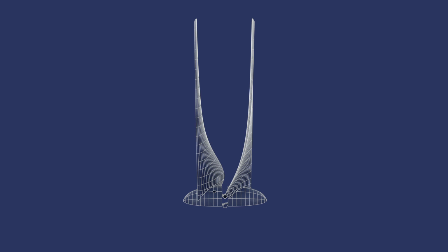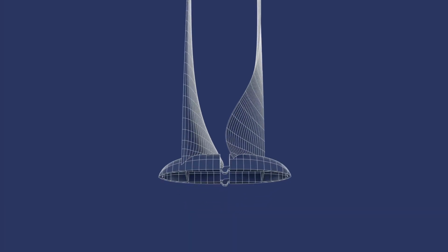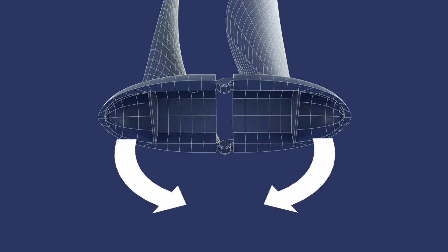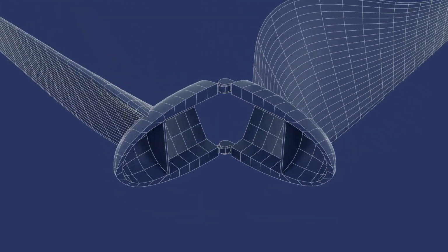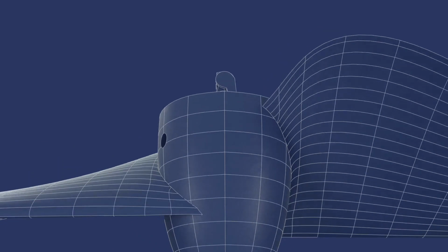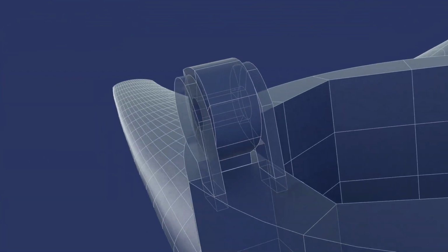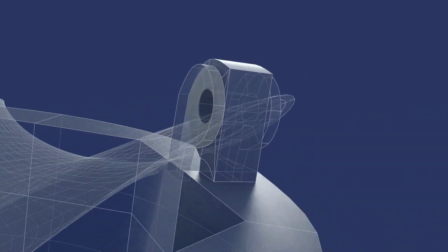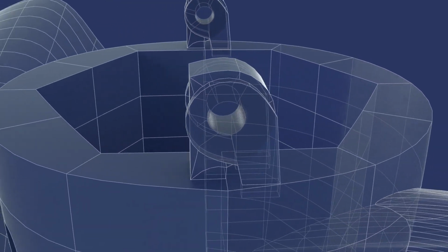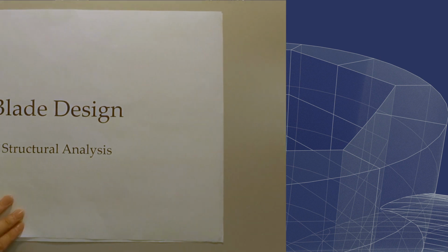It was found that the shape of the nose cone did not have large impact on the overall aerodynamic performance of the blades, especially at low speeds. Hence, a simple parabolic streamlined cone was designed with the purpose of minimizing drag. A simple hinge was designed to be able to fit our blade into the printing box. The main consideration of this hinge was its placement on the turbine. To avoid interferences and consequently turbulent flow on the wing, the hinge was decided to be placed behind the nose cone.